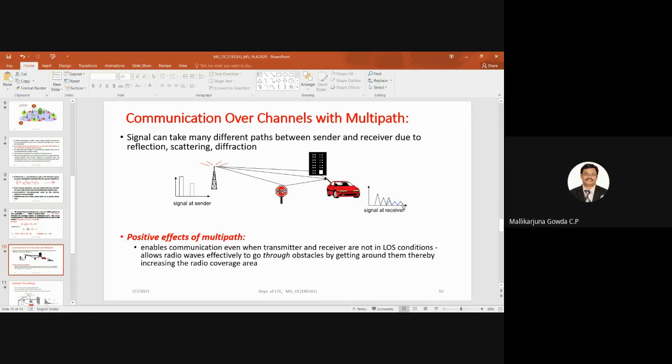As the signal travels through the channel, it gets attenuated, which is why the amplitude is shown less. The line of sight signal will have the highest signal strength compared to other path signals. There will also be overlap of those signals, because we are receiving the same signal with different magnitude at the receiver through different paths. That is known as multipath.